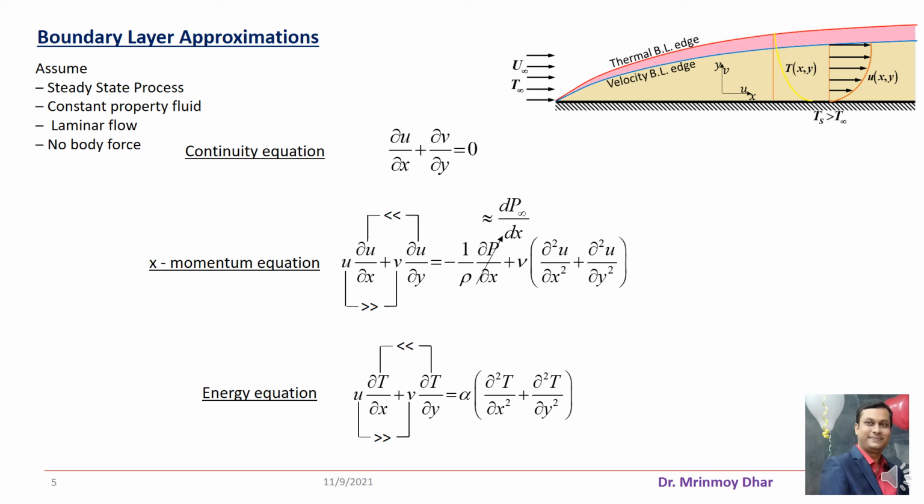So again here the small part is multiplied by a large part, so what comes out is a moderate number. So again in the energy equation, left hand side terms cannot be neglected. So we have come to these conclusions: the pressure gradient terms we have approximated, and then we looked into the terms in the left hand side of the x momentum equation and energy equation. We have seen that the left hand side terms cannot be neglected. These will remain in the final governing equation.